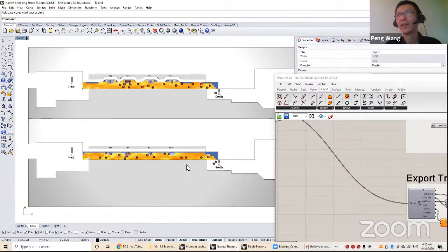Based on my test, I think PedSim works best when you have fewer than thousands of people, maybe hundreds of people. That will give you basically real-time performance. But if you increase it to thousands of people, maybe you will need to record your simulation as a screen capture and then play it back. So this is a hardware limitation.